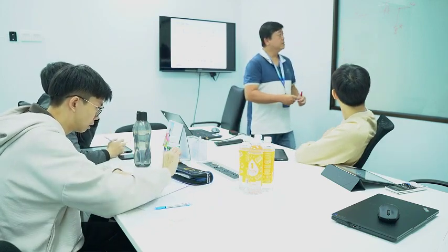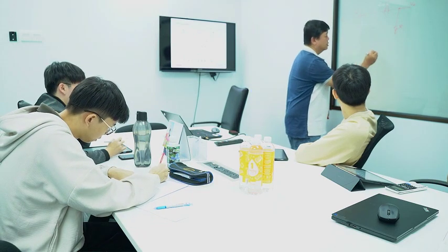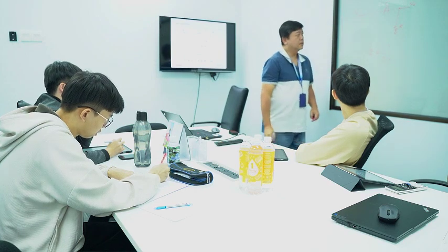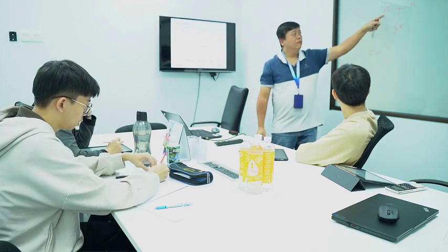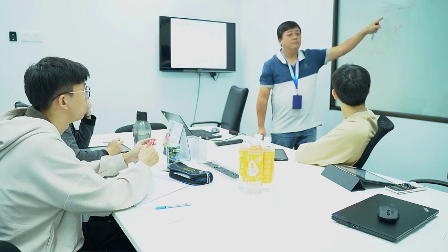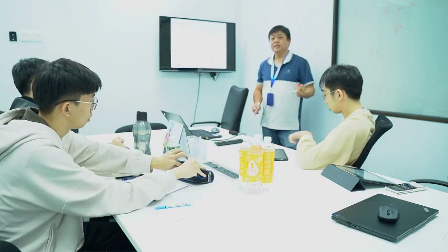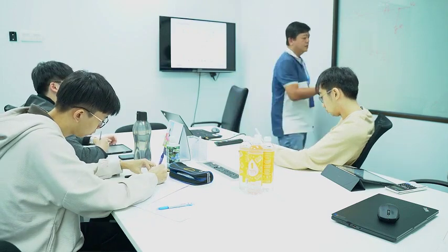Remember, the impedance across the capacitor is 1 over SC, right? So basically, as frequency gets higher, the impedance goes lower, right? When at high frequency the impedance goes lower, what happens? It behaves like a short circuit. That means everything will pass through there, right? This is the very first intuition you can learn about the high pass filter. It's a very quick way. Now we do the quick analysis on that.